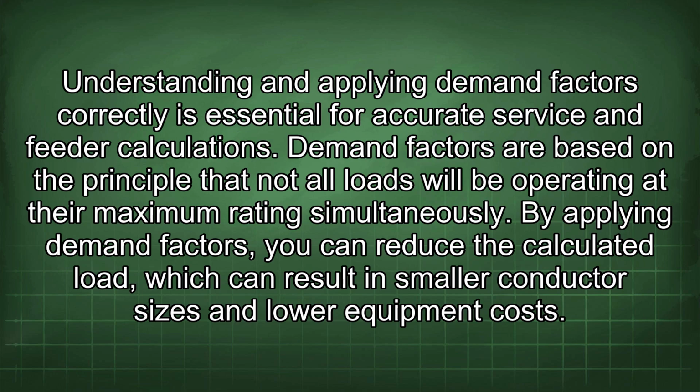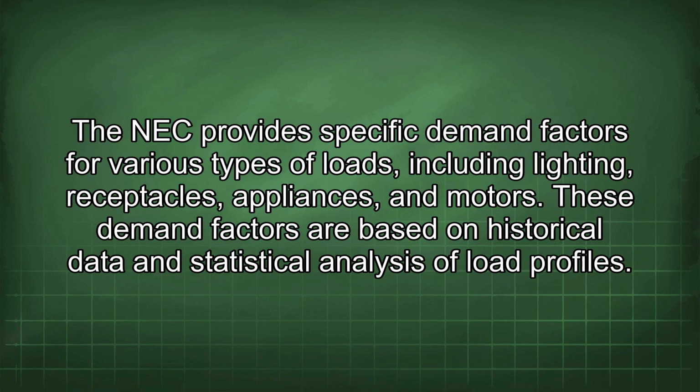Demand factors are based on the principle that not all loads will be operating at their maximum rating simultaneously. By applying demand factors, you can reduce the calculated load, which can result in smaller conductor sizes and lower equipment costs. The NEC provides specific demand factors for various types of loads, including lighting, receptacles, appliances, and motors. These demand factors are based on historical data and statistical analysis of load profiles.